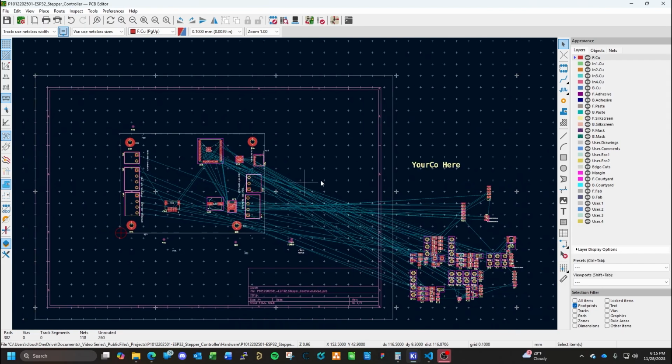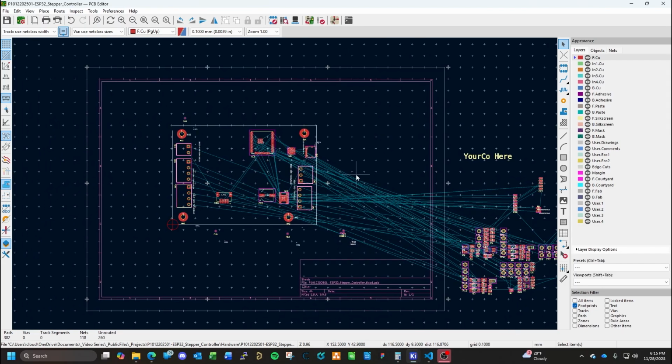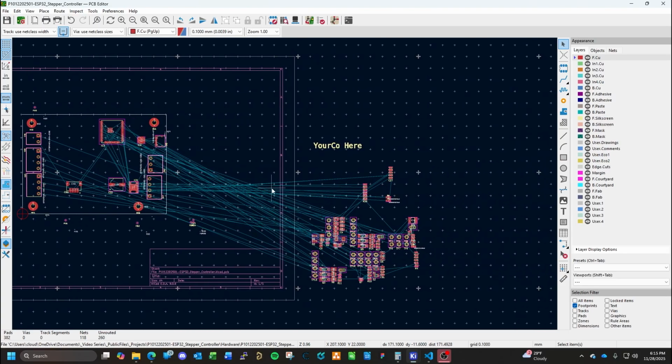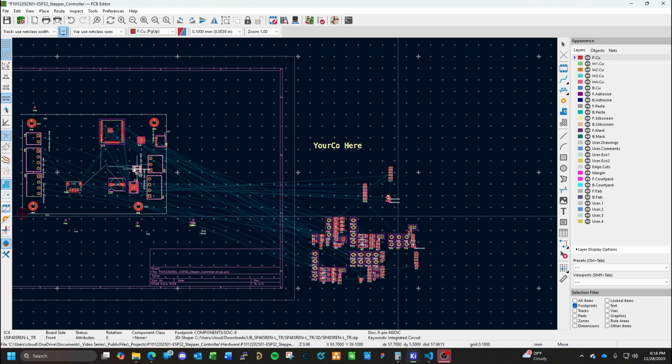Before we start messing with that, typically the power planes, once you select them in the layer stack up in other packages, automatically scale and understand their rules with the board and everything else. So before we go messing with that, let's make sure we can fit everything on here. That's the 45, for that fella. That could technically be on the bottom if it has to. Again, I want to try to put all the resistors and capacitors I can on the bottom.